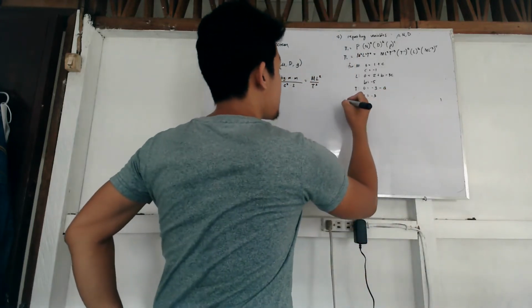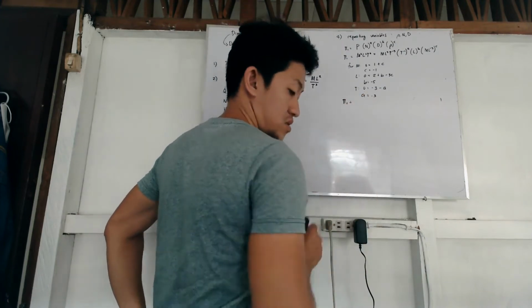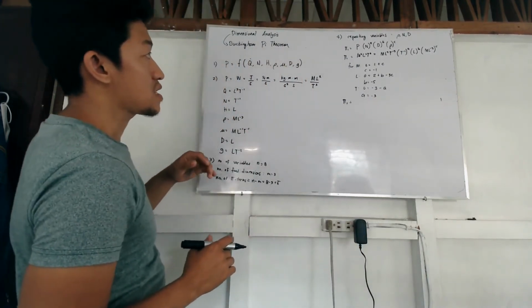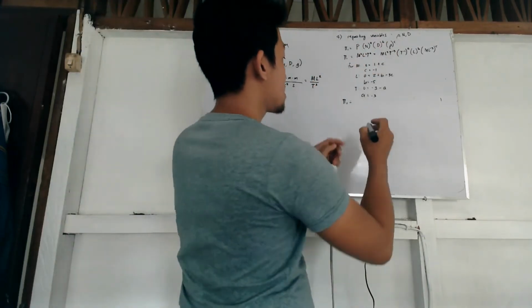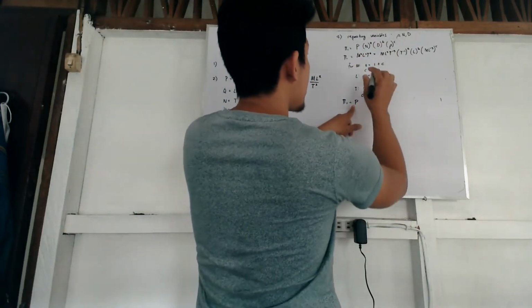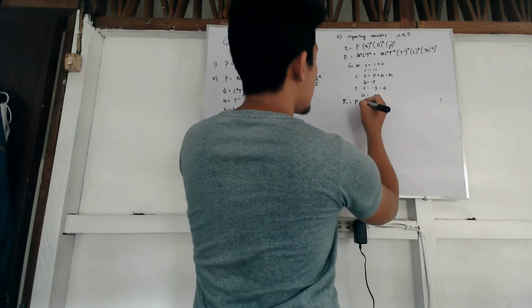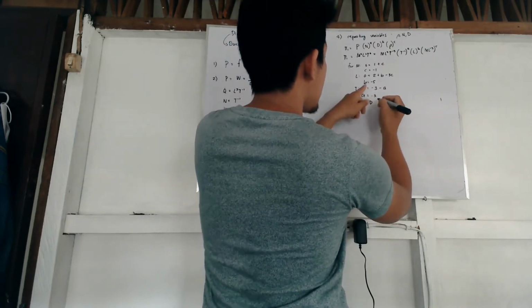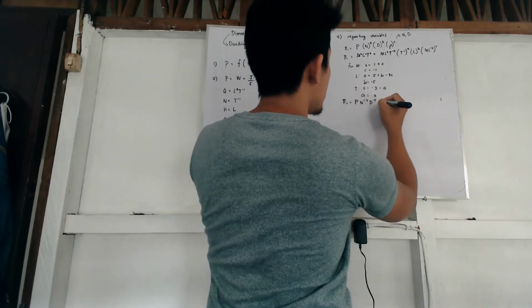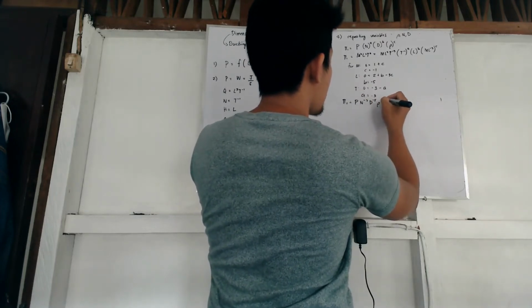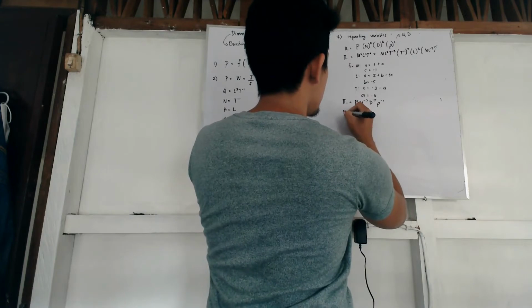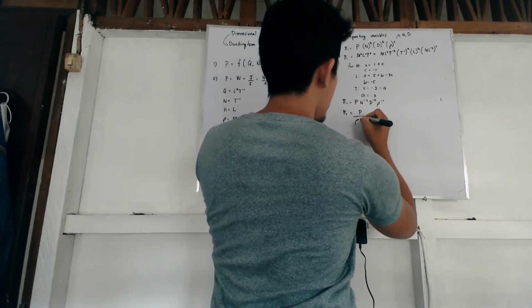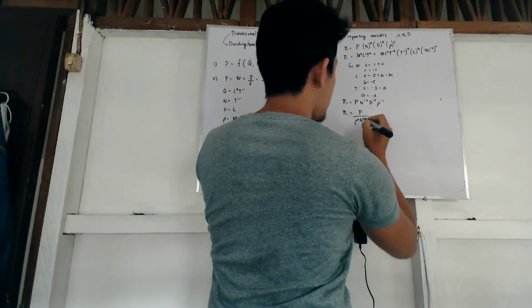Okay, therefore, your pi 1 is this. Look at this. Let me write it. P, then your N raised to A, N negative 3, D negative 5, rho negative 1, or pi 1 is P over rho N cube D5.